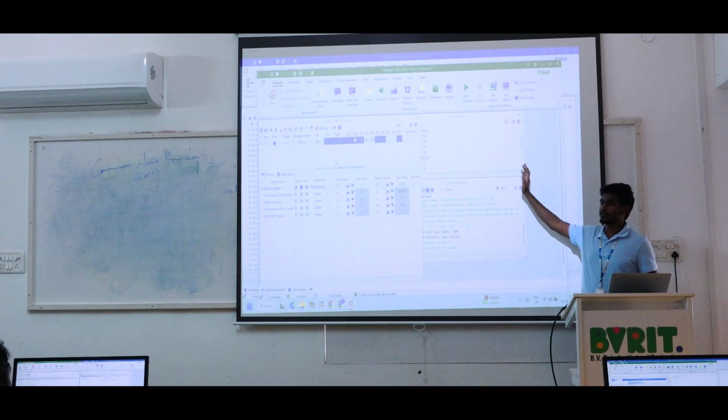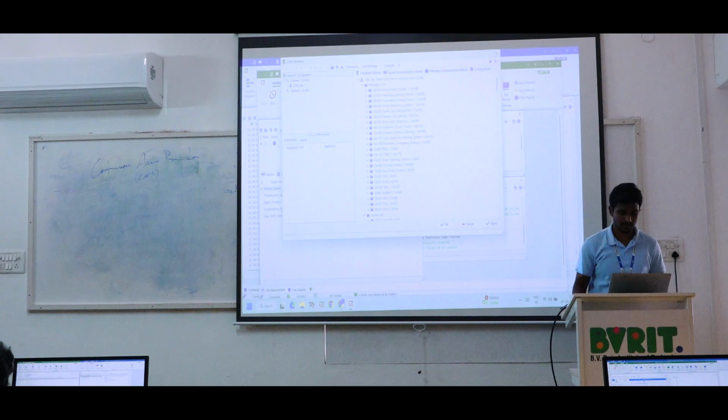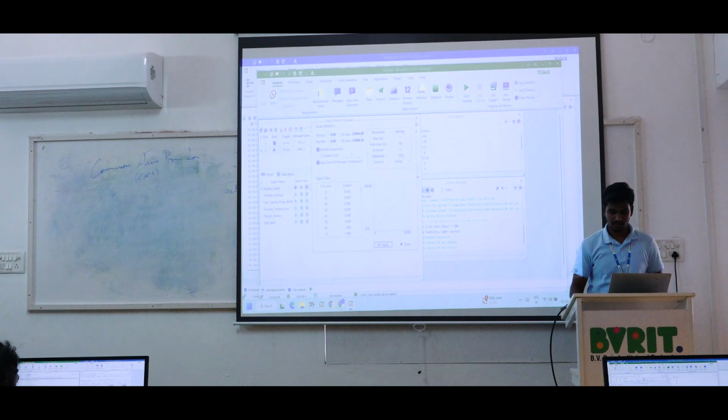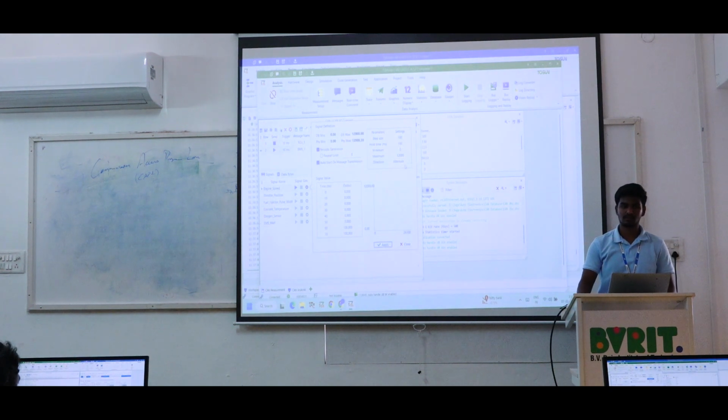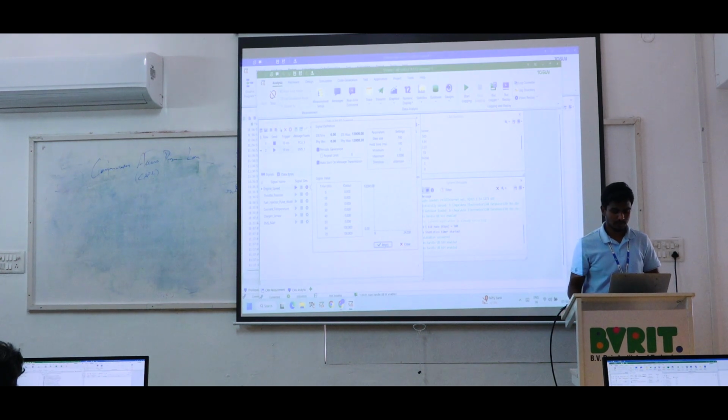Already we have transmitted the ID number 20. So I say, please add one more message, ID number 10, EMS. We just add the EMS, click OK. Set EMS vehicle speed, engine speed as a value range, and change the maximum to 12,000 and the step size to 100. The minimum is 0, the maximum 12,000, and the step size is incremented by 100. Okay, apply and then close.